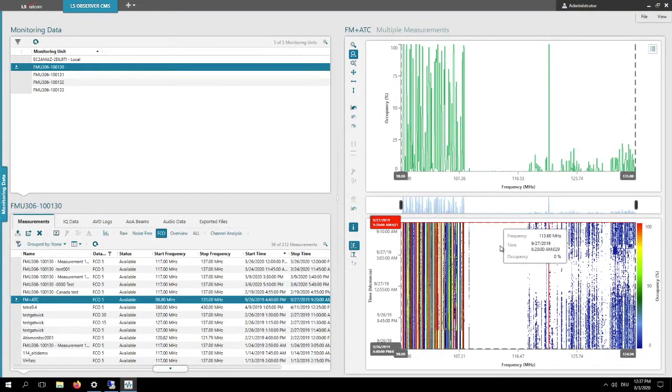For example, for a spectrum management process, you can now think about assigning frequencies here. And then you have everything which is a bit blue here. It's the normal ATC, so sometimes the pilot speaks, sometimes tower control speaks, and you can see the occupancy is about 39% or even lower, 10%. Here you have a red line with 100%. It's the ATIS transmitter of the airport. It's a permanent broadcasting electronic voice for the pilot, so it's permanently on air. That's why it's 100%.